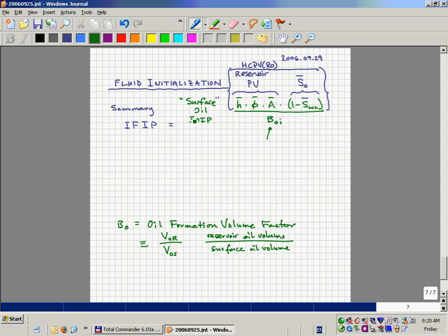Okay. So we've got a pore volume. If this is our reservoir, of course what you see is the bulk volume. The pore volume is this bulk volume times the porosity. And you remember what kind of porosity the chalk has? It's very unusual, up in the 40% range. That's this first term. You know, thickness, that could be the height. The area would be the circular area. And then the porosity, the average porosity might be 42% of this piece of chalk. That would be the pore volume.